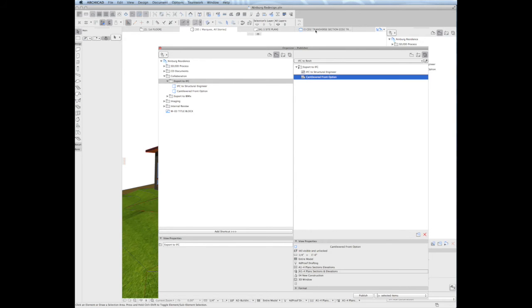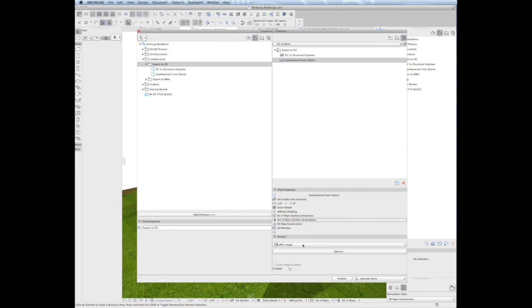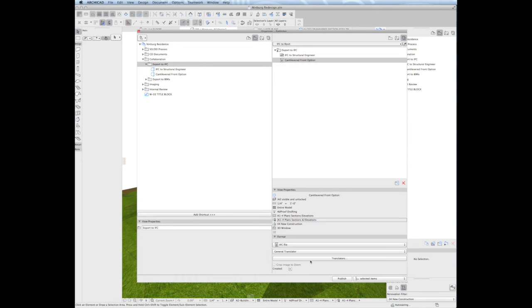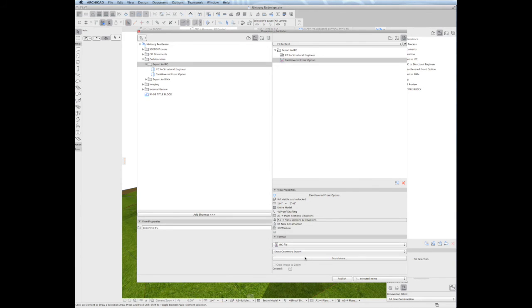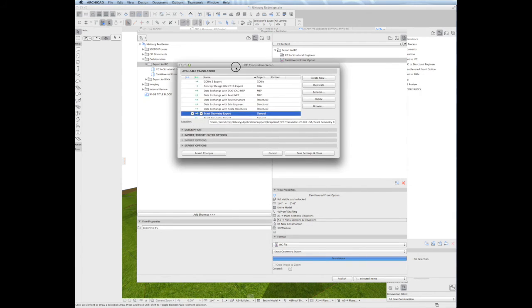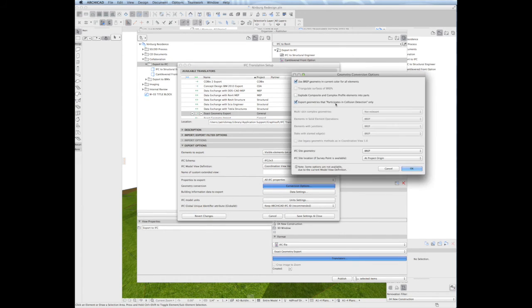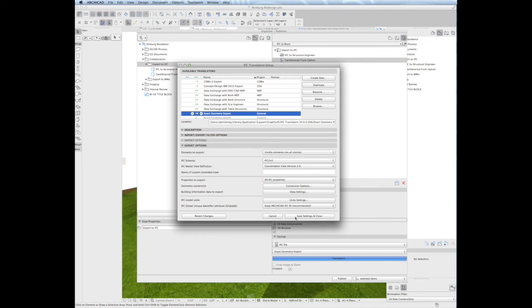And then from here, all I need to do is publish this 3D view that I saved out. There are a few things that I do want to check here, and that's that I am in fact saving it out as an IFC file, that I am using the exact geometry export option. And if I go to the translator settings here for exact geometry, and I go to the geometry conversion, notice that all of these are set to BREP, and that's basically just saying that the geometry will be represented as it's exactly shown here. That's really important when you're saving out to Revit in my experience, because Revit doesn't always